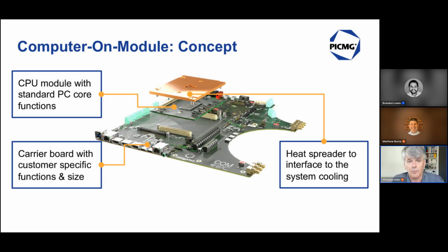All of those computer module concepts also feature a thermal interface called the heat spreader, which goes on top. This means it's a standard to the bottom, to the carrier board, where the connector and pinout are standardized, and also to the top side, where the heat must be transmitted to the system's cooling.